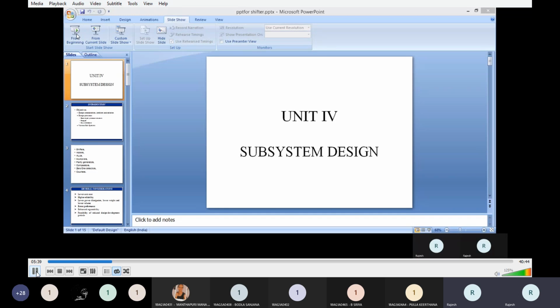The minimum transistor length, width, dimensions, so that no parasitic elements are created after fabrication of your design into the layers of silicon. Small examples like layout diagrams for a NOT gate, AND gate, NOR gate are covered in the syllabus, using both technologies, NMOS and CMOS. And if you are going for scaling of technology, presently it is 14 nanometer technology.